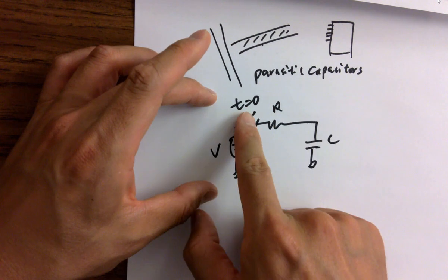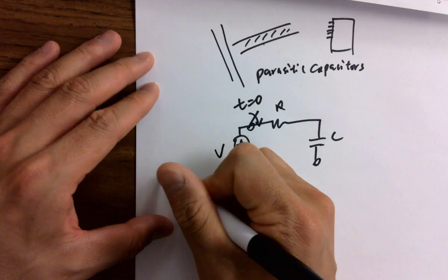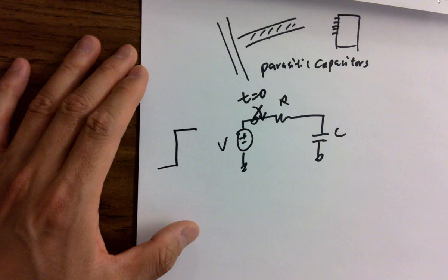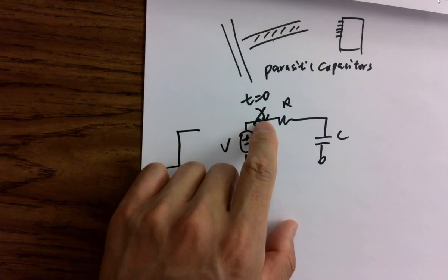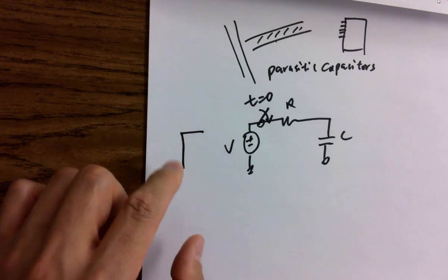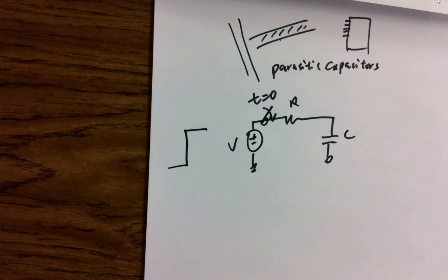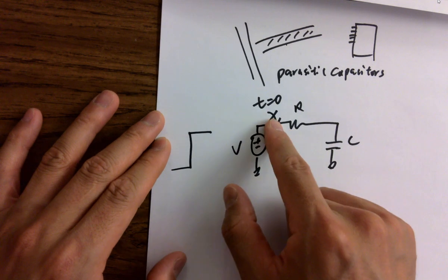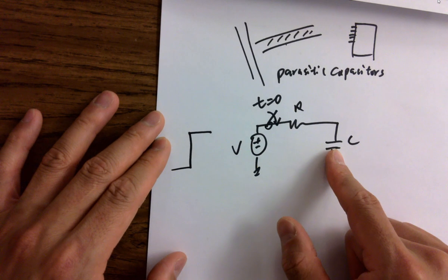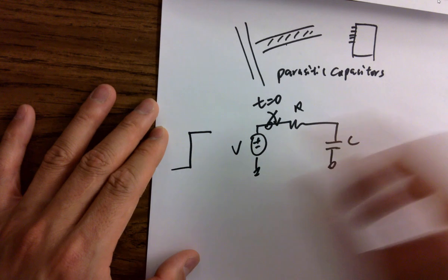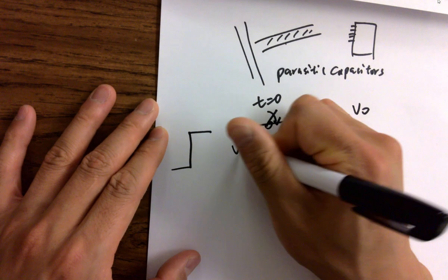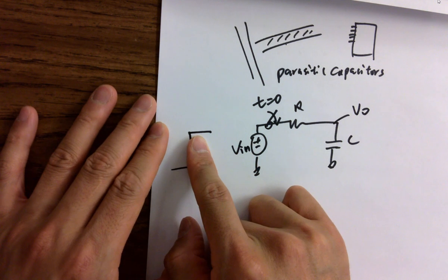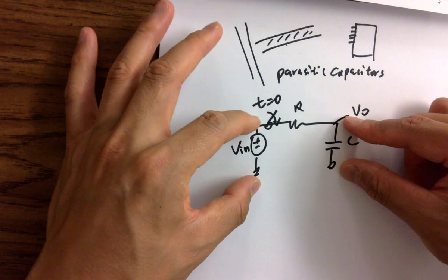Whenever the switch is getting closed, it's actually mimicking a 0 to 1 jump of the digital signal. There's no one flipping a switch there 24/7. It's a crystal, and the crystal is oscillating. So whenever it gets turned on, it's like a switch being switched on, so charges are being dumped into the cap and it's getting charged up. You look at VL, this is V in. VL is getting charged up. And eventually, can this voltage reach V in?